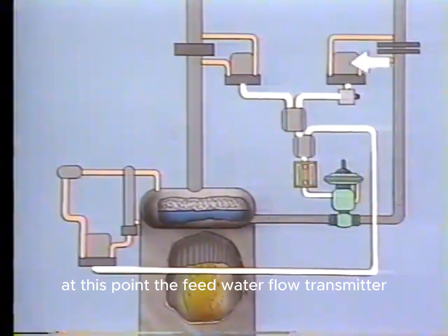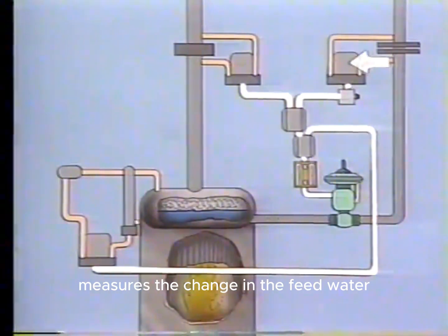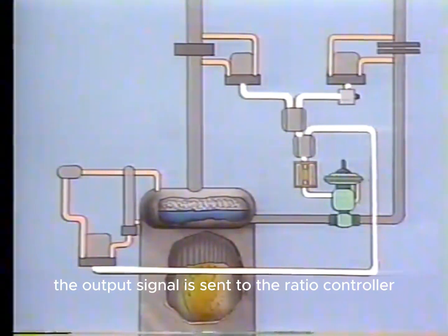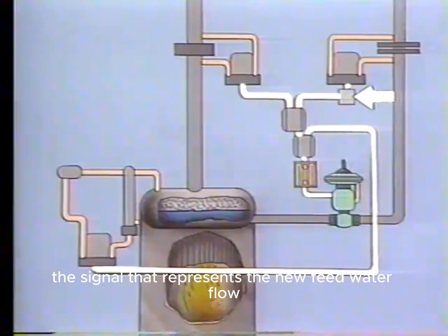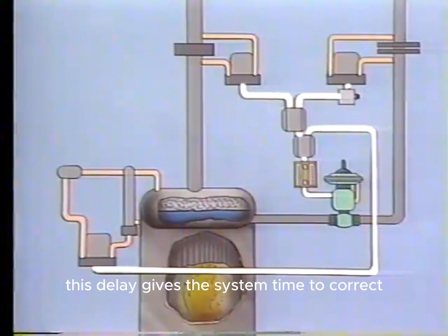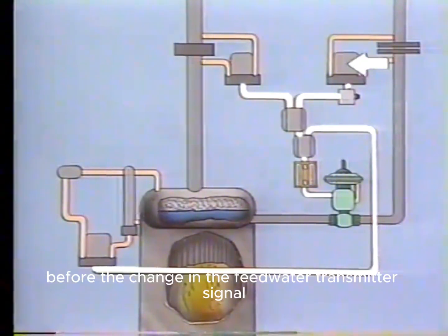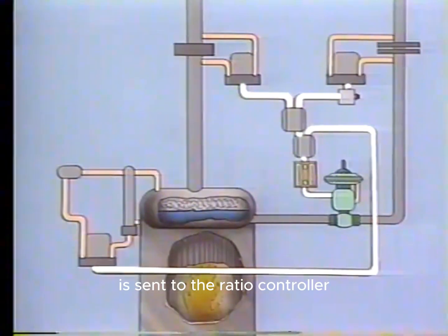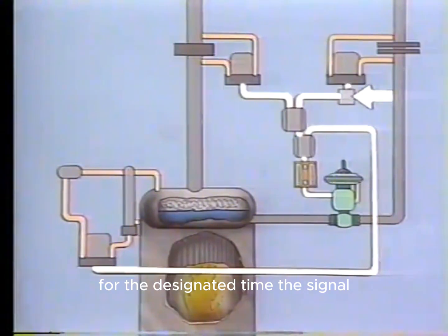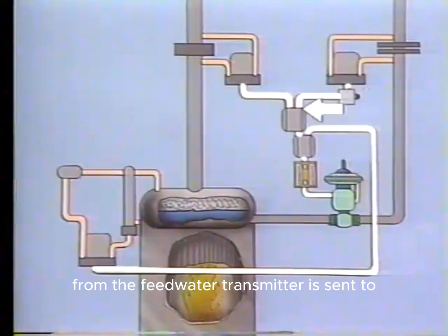At this point, the feed water flow transmitter measures the change in the feed water. It produces an output signal that represents the new flow rate. The change in the output signal is sent to the ratio controller through the volume chamber. The volume chamber delays the signal that represents the new feed water flow from balancing the signal that represents steam flow. This delay gives the system time to correct the water level in the drum before the change in the feed water transmitter signal is sent to the ratio controller. When the signal in the volume chamber has been delayed for the designated time, the signal from the feed water transmitter is sent to the ratio controller.